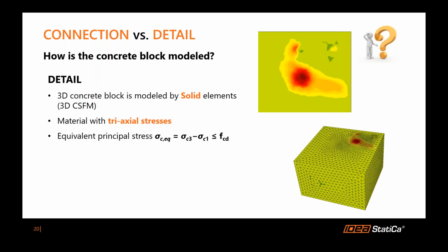On the contrary, in detail, the concrete block is modeled as a 3D finite element. The triaxial stresses are considered in the characteristics of the material. And as a result, we will receive the equivalent principal stresses that are compared to concrete strength in compression.